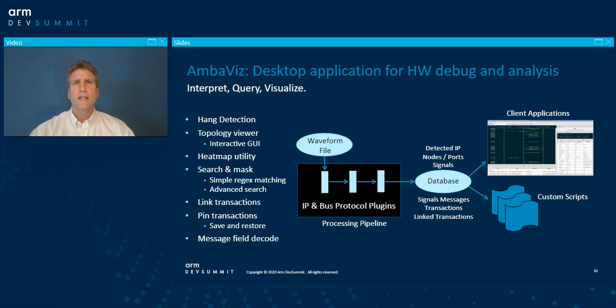I would also like to take this opportunity to introduce a new RTL debug tool for AMBA interfaces and interconnects that we're developing, and that will be available early next year. With the desktop application tool, you'll be able to extract information from standard waveform files like VCD, which the tool then correlates with the interconnect config and AMBA protocols to generate meaningful graphics and tables.